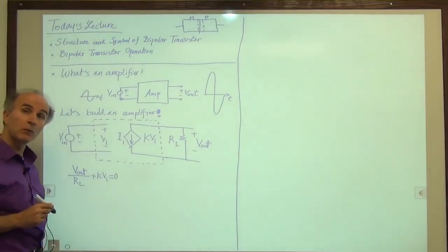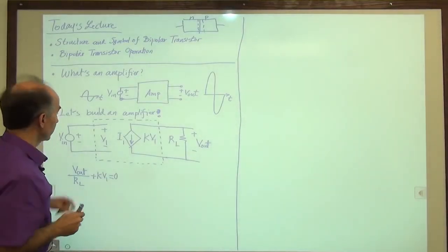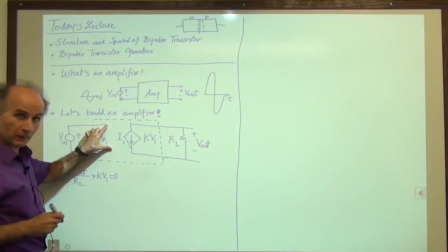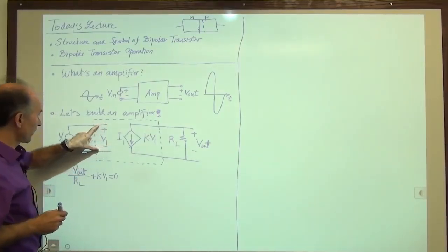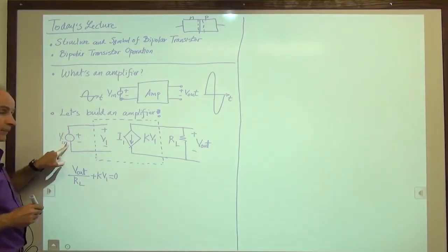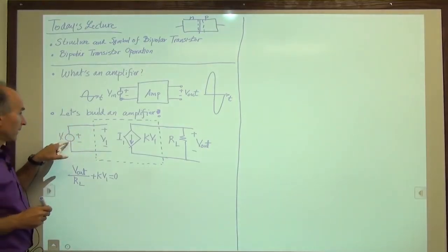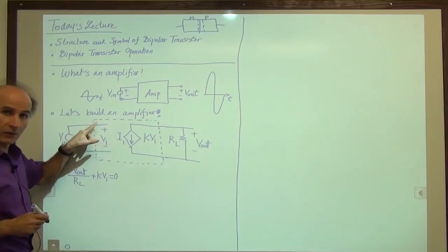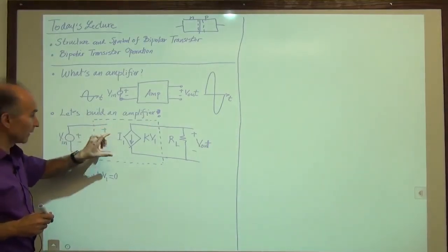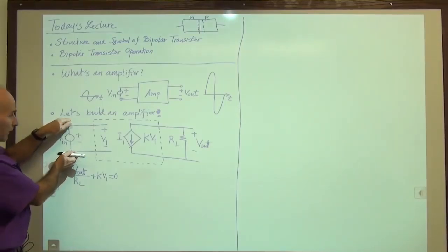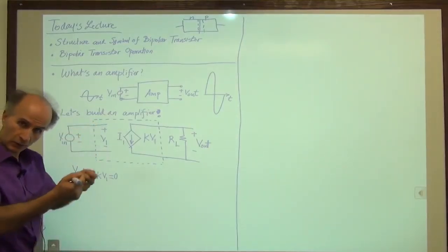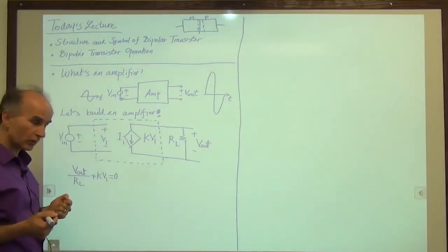Now, do we know how much V1 is? V1 is this voltage that is inside the device. But all we've done is we just connected two wires to the input. And because the wires are ideal wires and there's no current anyway, this voltage must be equal to this voltage, right? It's just like you took a battery and connected two wires to it, so you should still measure the battery voltage.